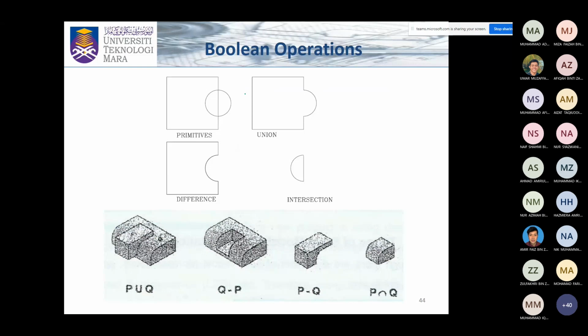So basically, in a Boolean operation in CATIA, let's say I expect you all to draw this model in CATIA. You probably just draw a cuboid, and then you might round this corner. Then somewhere in the center of the plane, you select the center and add another cube, then merge it, extrude it this side, mirror extrude or something like that, and you will get one shape only. And then if I say now I want this model, you'll have to redesign this whole thing.